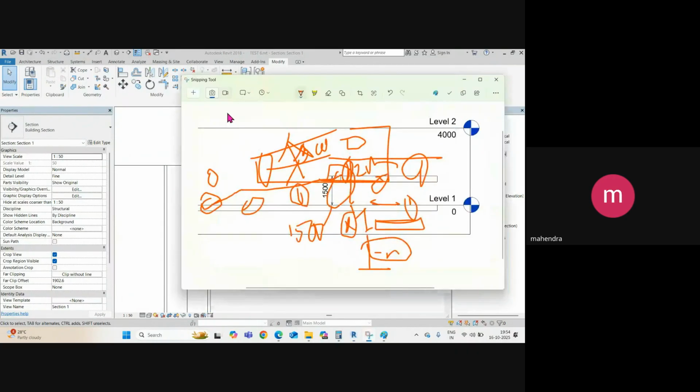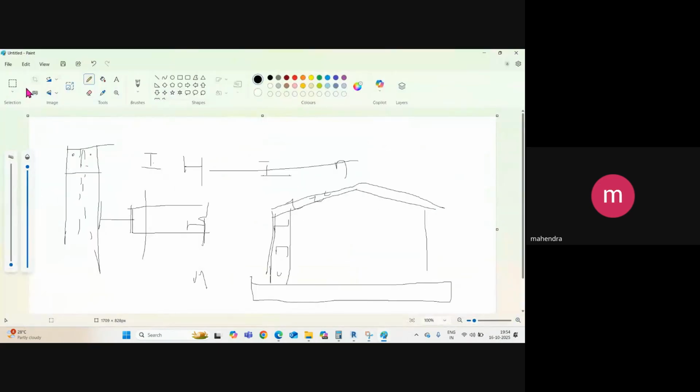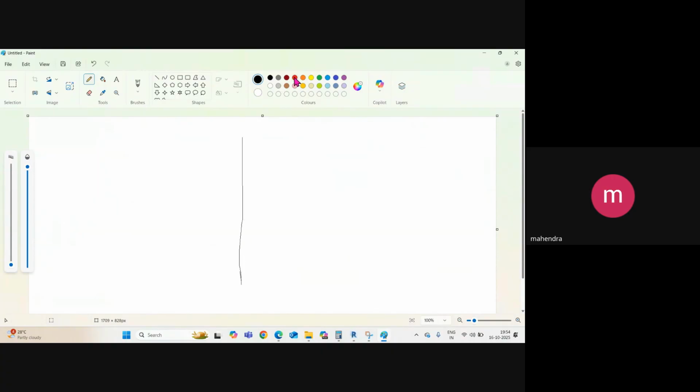Right, then here it's very difficult to give the end plate. So for example, I will give an example here: new and say okay. So suppose this is my column. I will increase this thickness. Okay, so this is my column and this is my web here, right? Like that. So I want to give the plate here, and here. And here is my I section, right? So you need to give some gap here. Your column should be above by at least 25 to 50 mm.